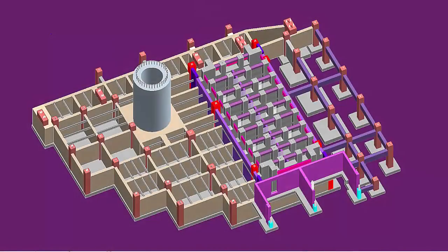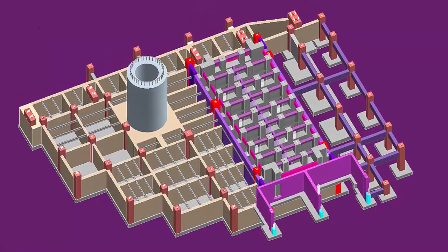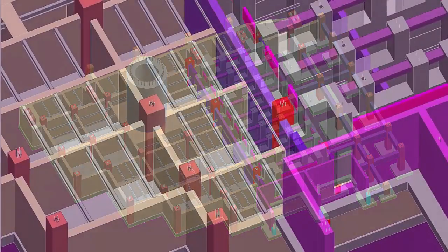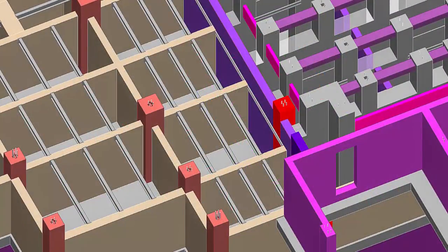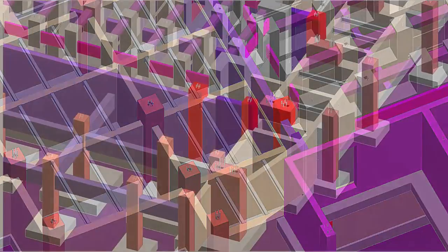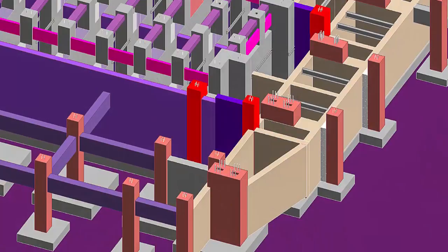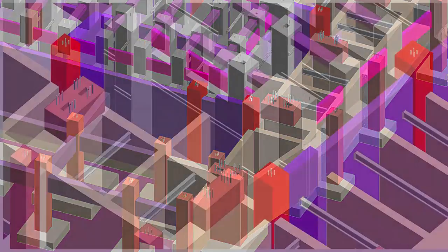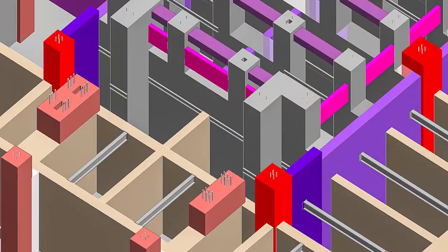The display of the structural components of this Revit model is determined by a set of rule-based filters. Rule-based filters enable the display of a structural member to be dependent on the properties of the structural member. In this series of views, the display of the piers and walls is determined by the top of concrete elevation of each. Items with the same top of concrete elevation are displayed in the same color. The building piers on this foundation have two different tops of concrete.